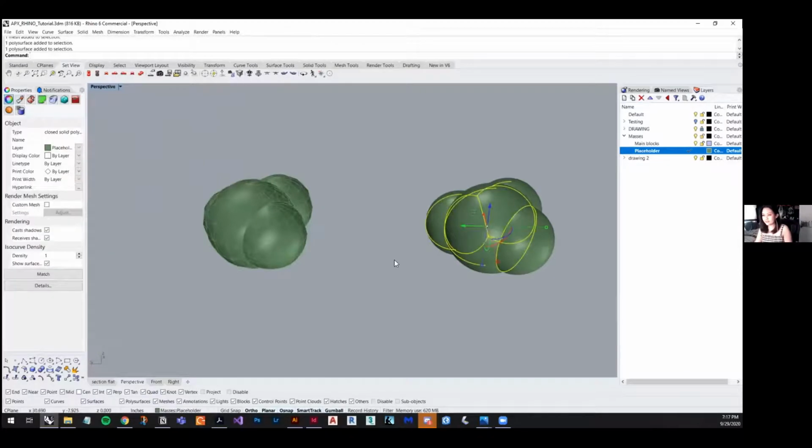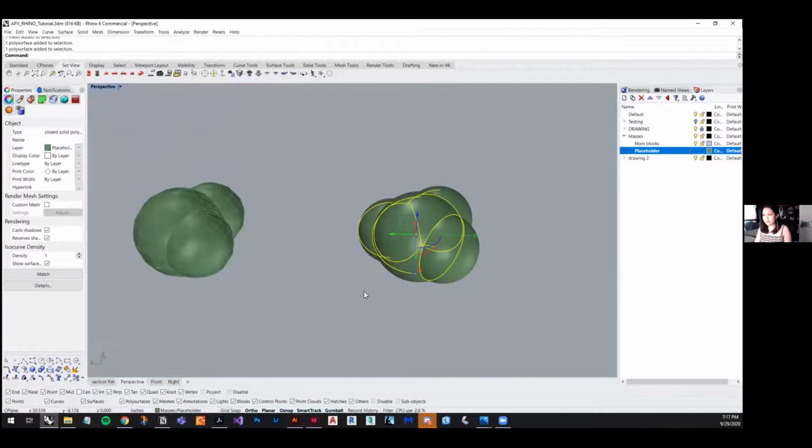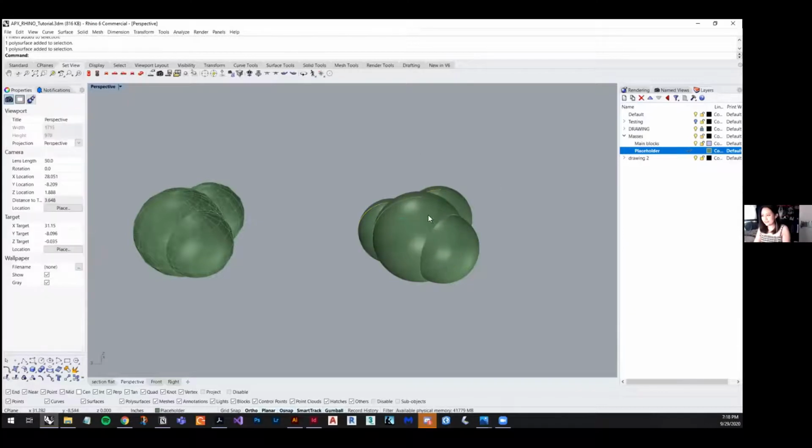Poly surfaces and other surfaces in general on Rhino usually use a thing called NURBS. The difference is that with AutoCAD, they use meshes, whereas in Rhino they use NURBS mainly. So NURBS, think of taking a bunch of lines and calculating, like some calculus thing, and if you guys are into derivatives and whatnot, that's what's happening with this one.